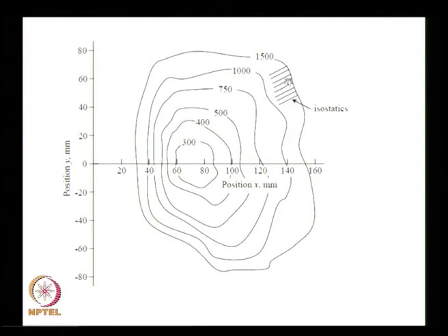So, the idea is definitely at the end of these cracks the failure strain of the coating is reached at that point in the specimen, but this is obtained for a load of 1500 newtons and this contour is obtained for 300 newtons and so on. So, the idea is when you conduct a brittle coating test, this is what you will mark.